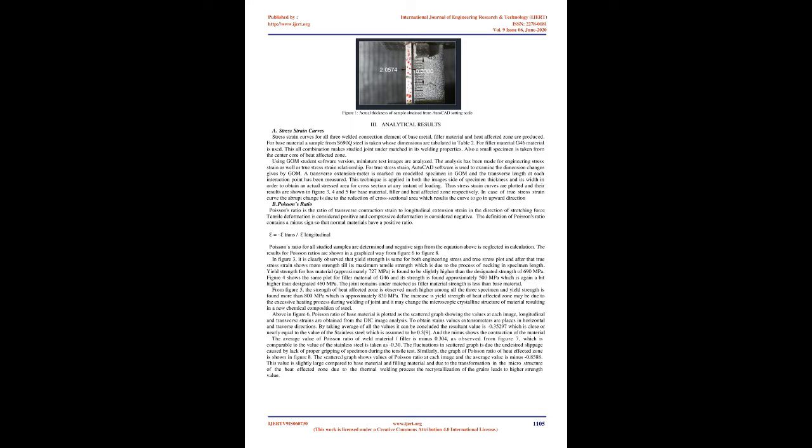2. Experimental study. Commercial software GOM Correlate has been used for DIC analysis of the miniature tensile tests, in the free version for students. It only allows analysis of a 2D surface using one camera only. The basic principle of DIC is the tracking of the same image points located in the two digital images of the test specimen surface taken before and after deformation.